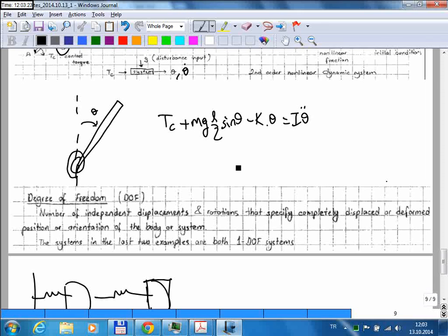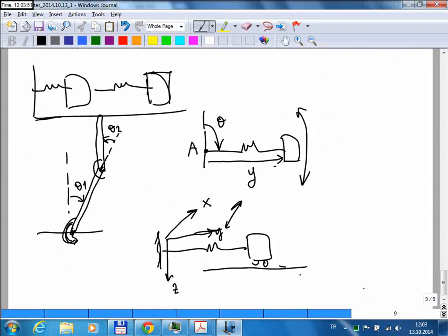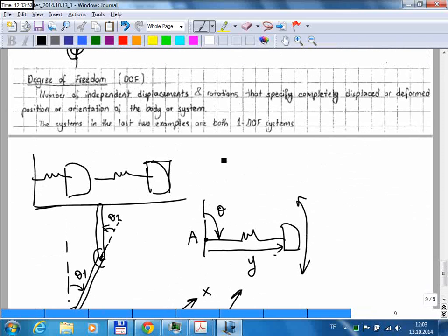Considering my explanation before, if you see a helicopter flying and you take a picture of it, to represent the orientation and position of the helicopter, you need 6 variables. You will need 3 of them to indicate its position, and then you will need 3 angles to represent its orientation with respect to the Earth. Okay? Do you have any questions?